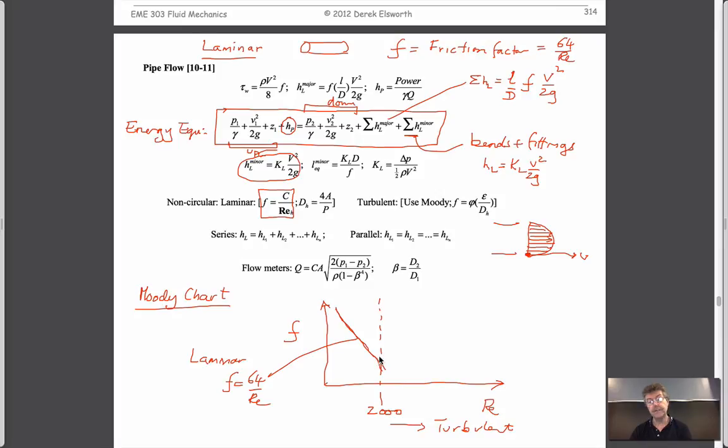And it'll turn out that we end up with a bunch of lines, and we're kind of jumping ahead of ourselves right now. And we said that if we only have two pi groups, we would have a unique expression. So if pi 1 was equal to the friction factor, and pi 2 which is Reynolds number, so this is a velocity, a diameter, a density, and a viscosity.